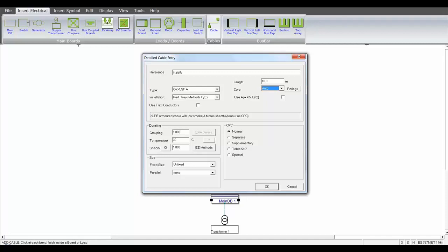If I wanted to make a much larger project, I could go to the edit menu. I could recall the general information. I can go into defaults, and then I can change the area of the screen. Then when we go to the view menu and select zoom all, I have a much larger area. I can then go to the home screen.